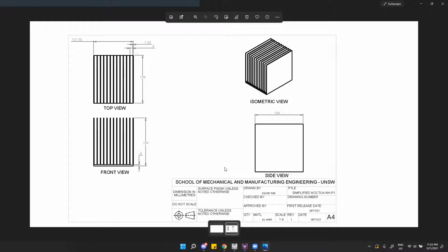Hexahedral meshes are economic with the number of elements because the same degrees of freedom for one hexahedron corresponds to 6 tetrahedral elements. Increasing the number of elements will not increase the size of the global finite element matrices, but the computations for one hexahedron is much more economical.